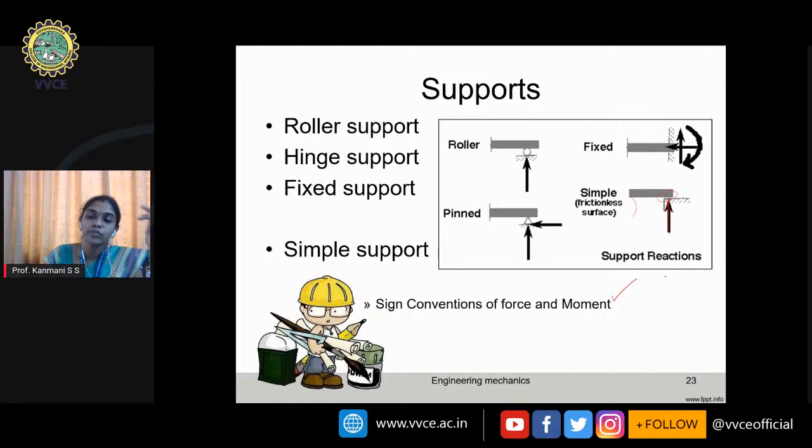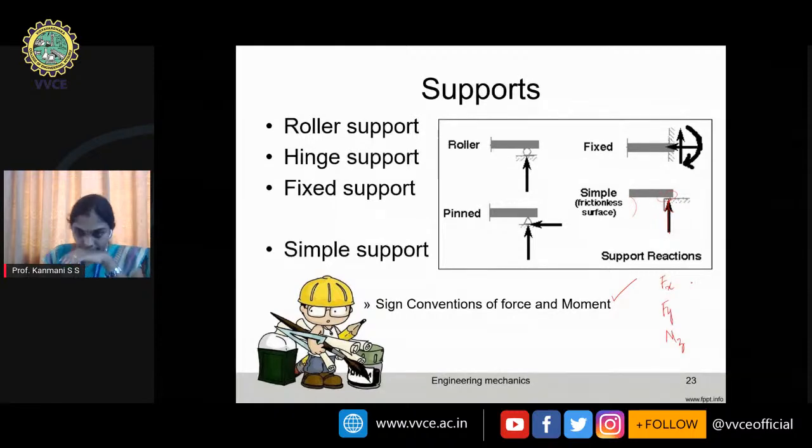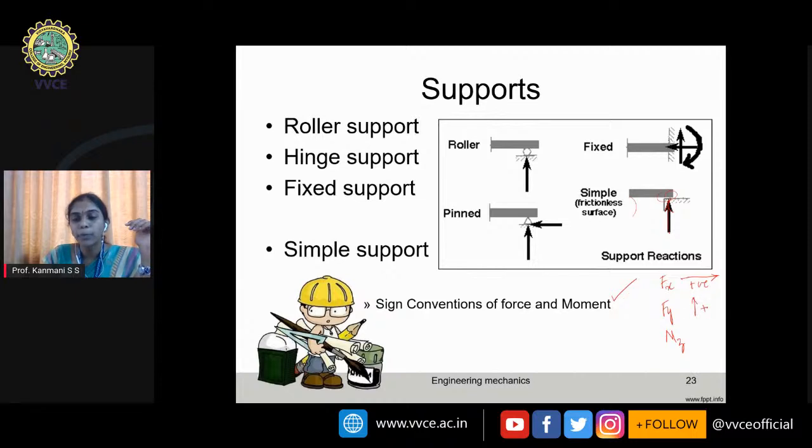MZ. Remember the sign conventions that I'm using here in this session: forces moving rightward are treated as positive, forces moving upward are treated as positive, and moments rotating about the z axis in the clockwise direction are treated as positive. So clockwise moments are positive, rightward forces are positive, and upward forces are positive. These are the sign conventions that I'm going to use for force and moment.